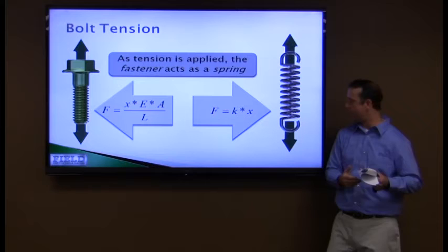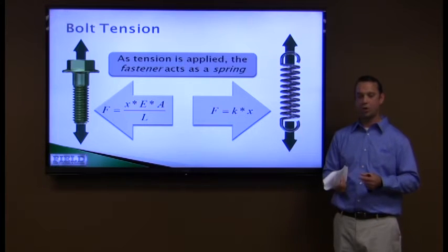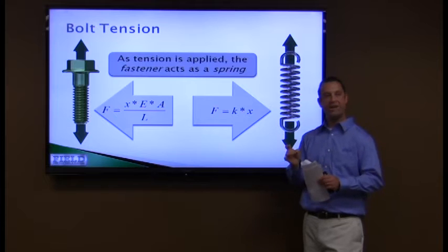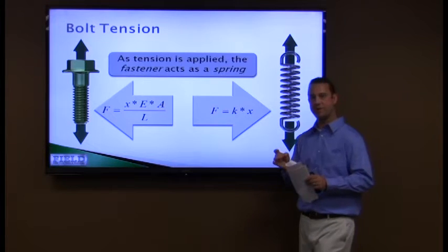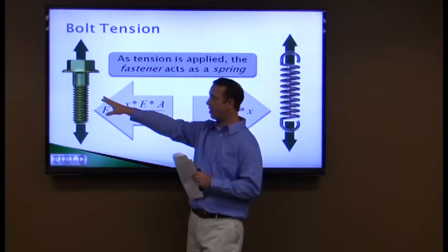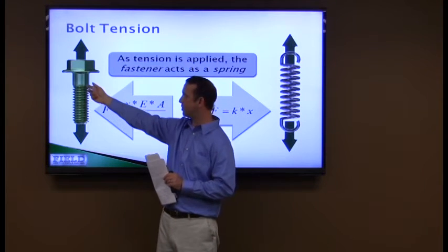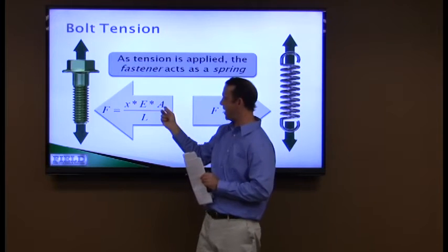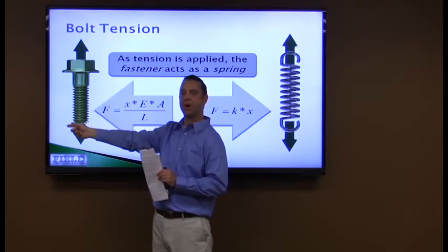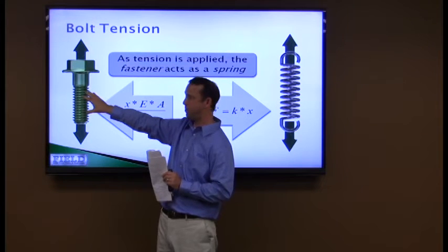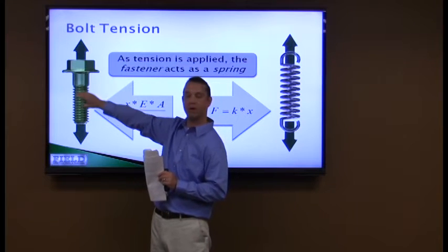That's kind of why in real critical bolts, like on connecting rods and in engines, you'll see a neck-down portion underneath the head where there are no threads. They do that for this reason right here. When they shave this down and make this smaller in those applications, what they're doing is making this A number right here constant throughout the fastener. So you get one constant amount of stretch, as opposed to this way, where you get two different amounts of stretch right there.